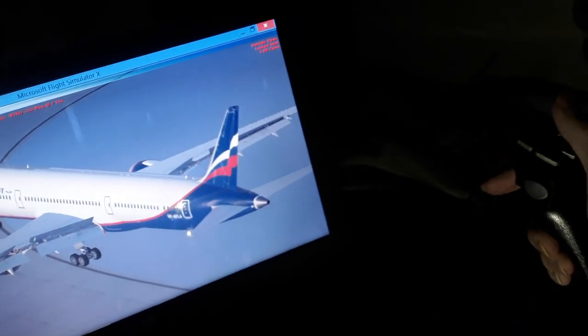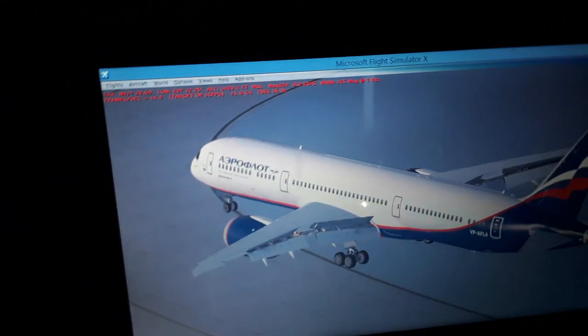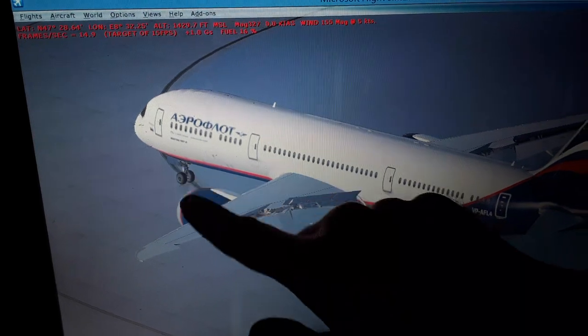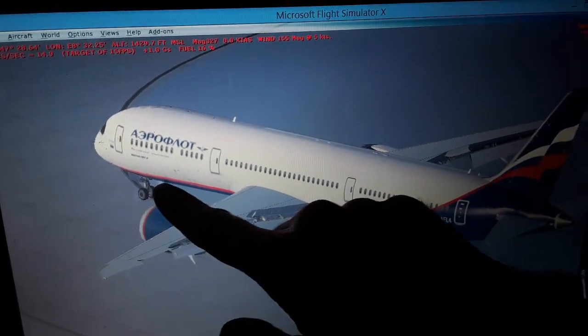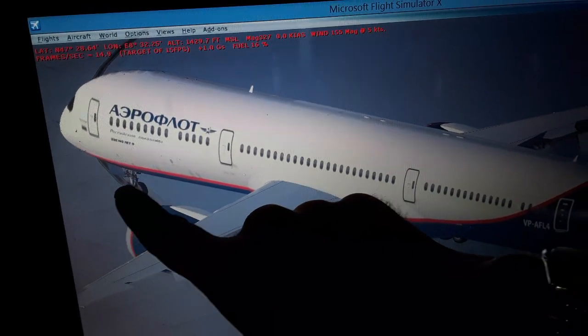Above 45 knots the rudder is becoming aerodynamically effective over here. So you take control above 45 knots, more with the rudder, less with that. It decreases above 45 knots from 76 degrees deflection either left and right to 7.6 degrees only.